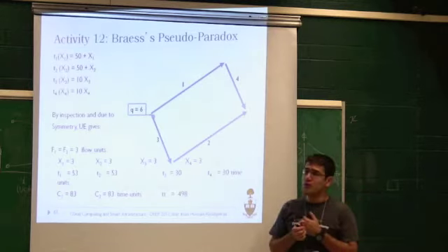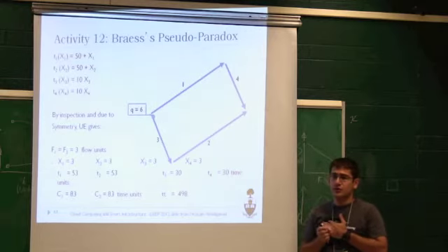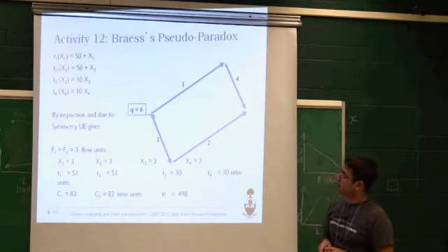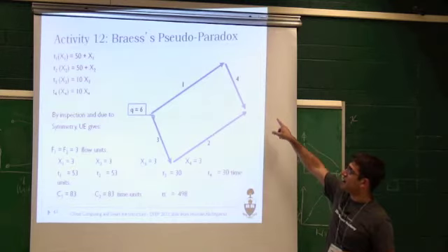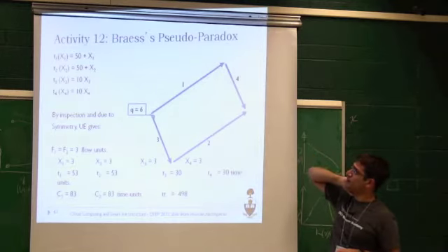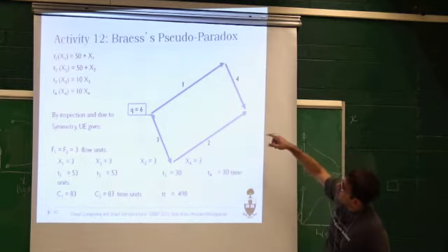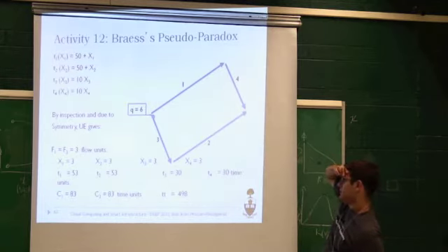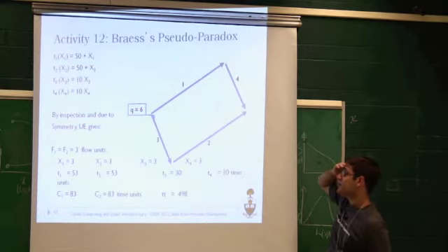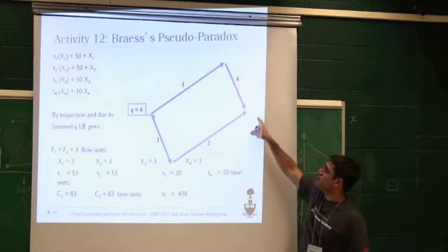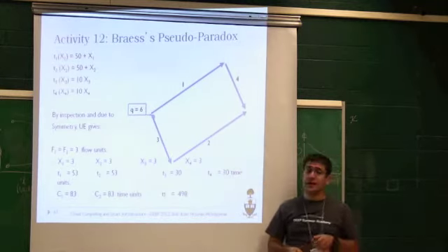On link 1, how many vehicles are going through? 3, right? So the time for the vehicles is 53. And how many vehicles are going through link 4? Again, 3. That's why I have 30 plus 50. Is that correct? 53 plus 30, 83. That's why the travel time for one vehicle to go towards there or towards there is 83 time units.